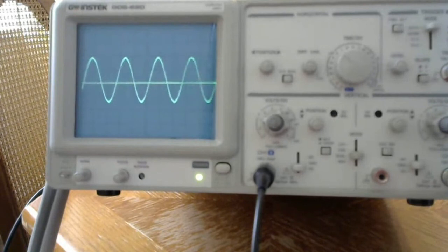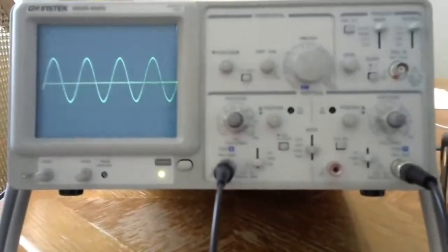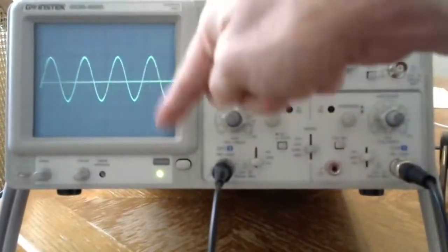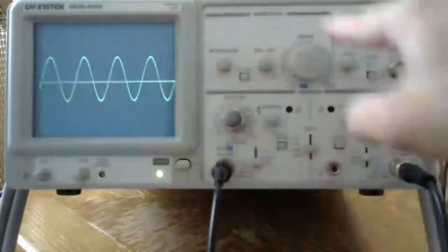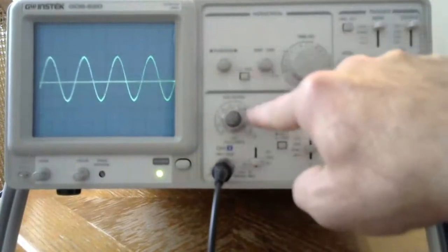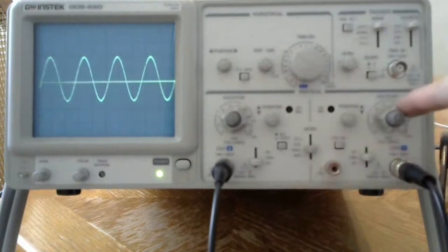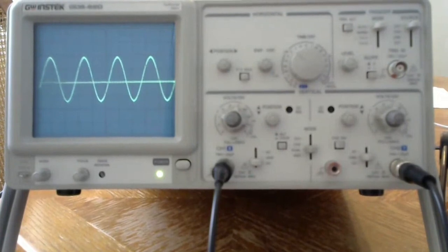Okay, so that is basically what an oscilloscope is. It's a measurement device that measures voltages, signals that are changing very quickly in time. The voltage is along the y-axis, and the time is along the x-axis, and the scale for the time is set by the time base. The scale for the voltage is set by the voltage per division here for channel 1 and here for channel 2. Okay, and so you measure voltages by taking your probe and looking at a particular location on a circuit.